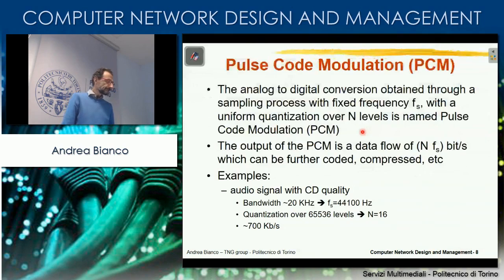That's the so-called PCM, pulse code modulation, which, as we know, applied to a voice signal gives this speed of 64 kilobits per second, which is derived from a 4 kilohertz bandwidth, which makes 8,000 samples per second, and with the choice of using 8 bits to represent the amplitude of our signal, which means 2 to the 8 different levels. Okay. This is called PCM in general.